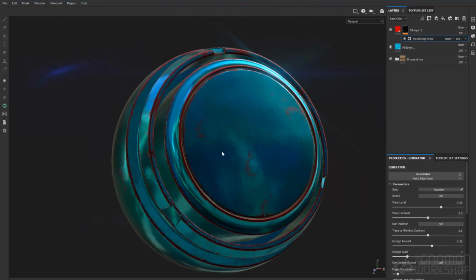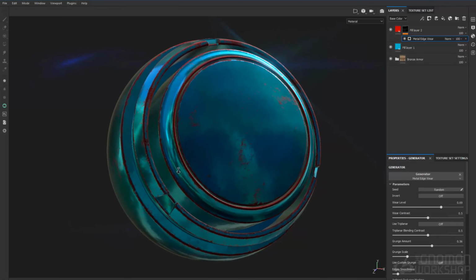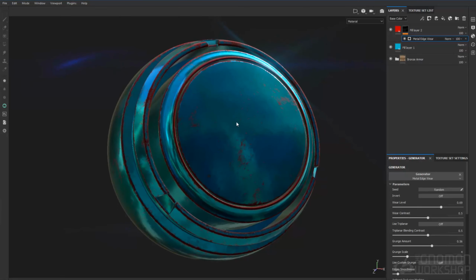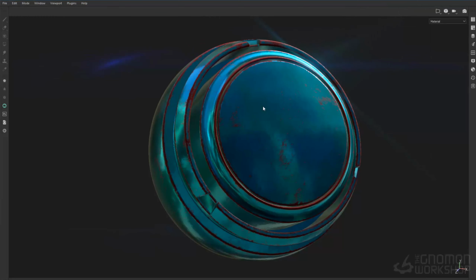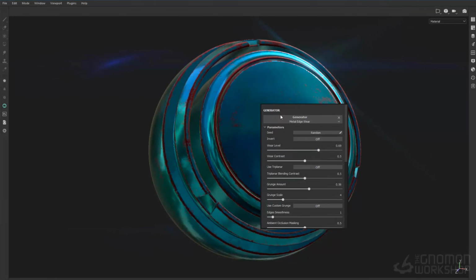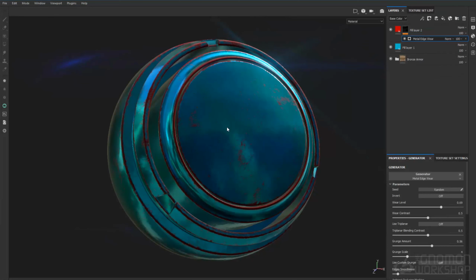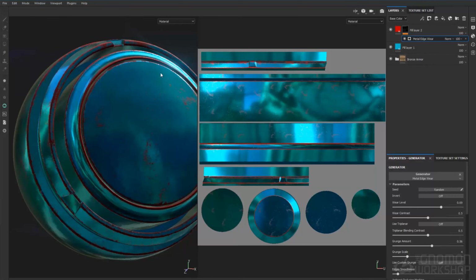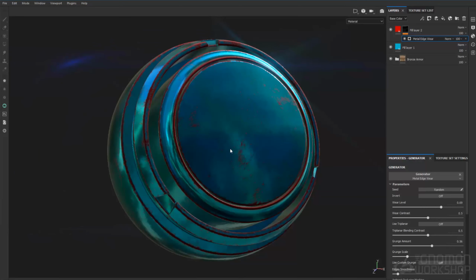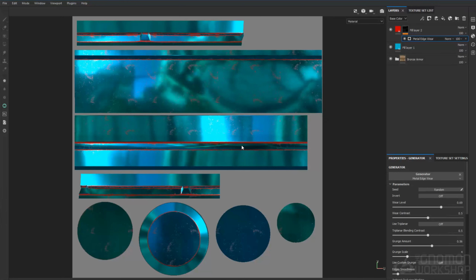Since we are also talking about viewport keys, let us make sure to remember that we can use the Tab key to allow us to get a bigger interface. We can use the right click button to have access to different parameters. We are going to go back to that later. We can use F1 to have a dual view, which allows us to see 3D and 2D. F2 to be 3D only. F3 to be UV. When I'm on my UV, I can actually paint on my UV, right?